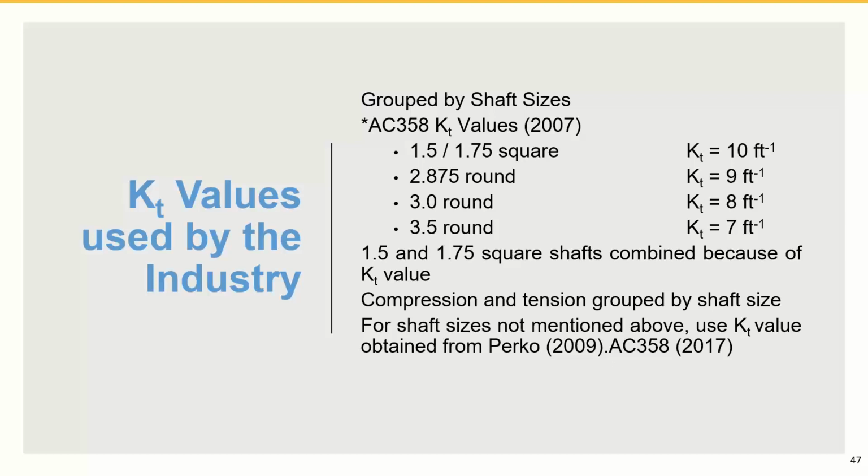And also, torque is indicative of soil shear strength. There are so many people with papers talking about installation torque being really correlated with soil strength. I forgot which one, but if I find it, and if anybody wants it, I'll be happy to send it to them. So torque is indicative of the soil shear strength. As a matter of fact, AC58 clearly says what to do if, for instance, you have to install a helical pile on some job site but you have no soil information at all, no soil reports. What do you do?